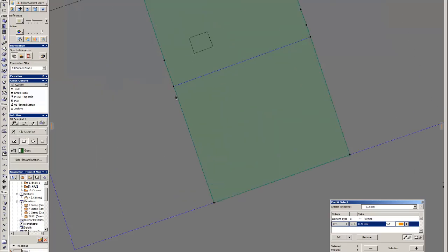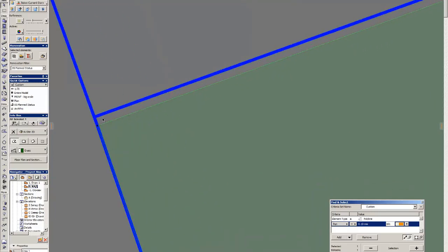Using the space tool, the magic wand, we will create the meshes. We separate the mesh here because we need separate meshes. The southern one will be the lot we are interested in, and the northern is the adjacent lot. As mentioned before, we will simplify the geometry here. They have another point which we will also draw.